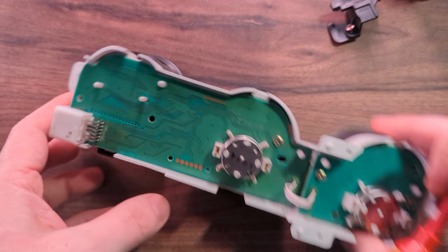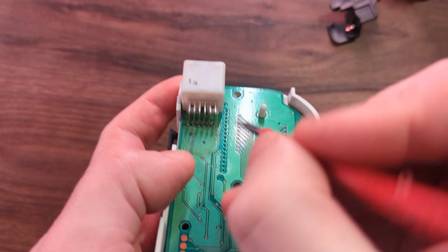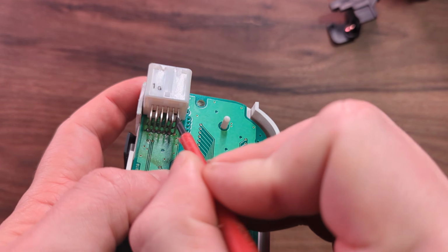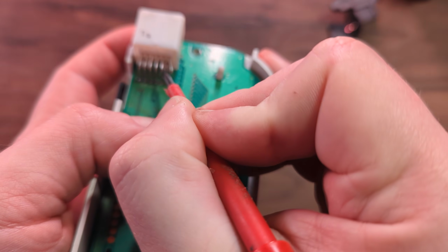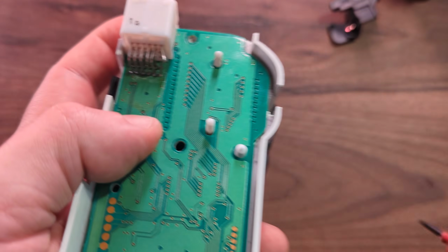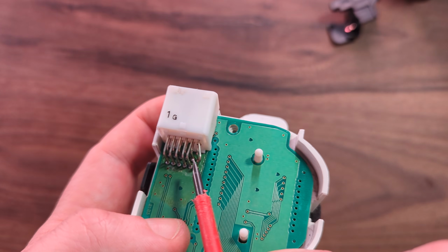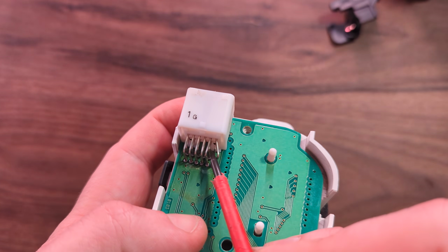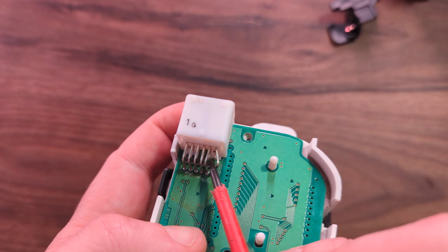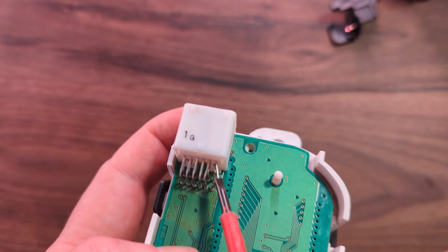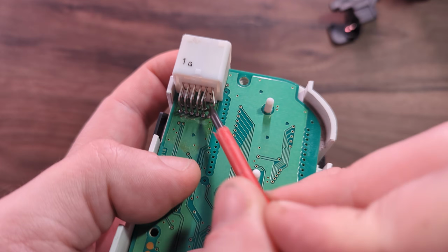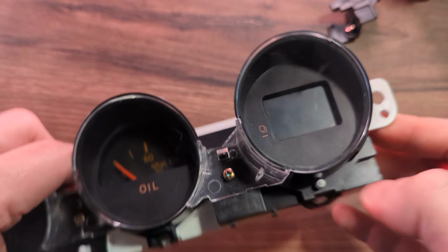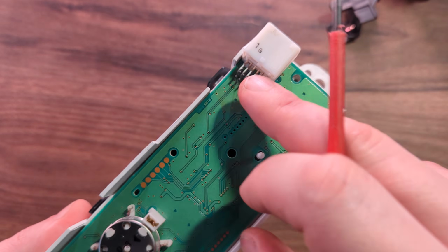And in order to do that, we're going to have to do something a little bit clever, and it's this. We're going to have to take this out to the car, plug it in, and we want pin 8, which is the one underneath here. It's second one in. So if I bend this to the side, bend that to the side, so I've got space but still nothing's touching, I can get my multimeter through here, touch that pin, second one in, so number 8, and the ground, which is this top one here, and test what the voltage is in between those 2 pins.